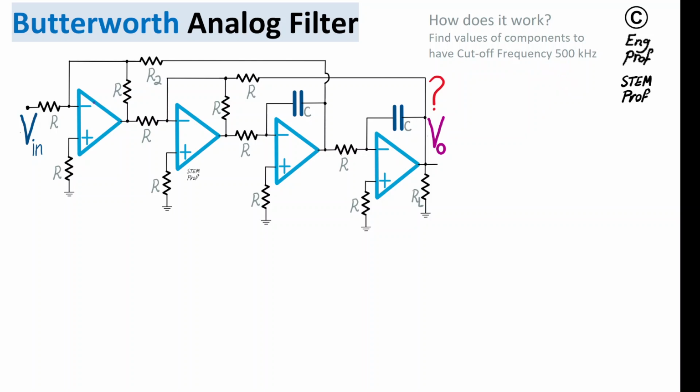Okay, so let's make the assumption that the op-amps are properly biased. By properly biased, I mean the supply voltages, whether double supply or single supply, should be there correctly. Also notice that we have the proper connection at the output of the op-amp via a component like a resistor or capacitor to the inverting, or negative, input terminal, indicating the existence of local negative feedback for each op-amp. At the same time, the positive terminals of all op-amps are connected to ground, so the voltage at the positive terminal is 0.